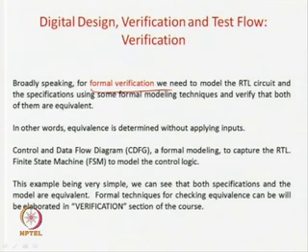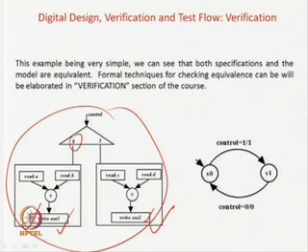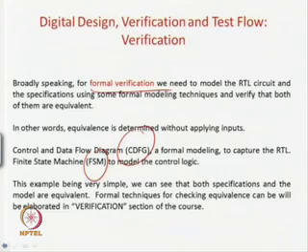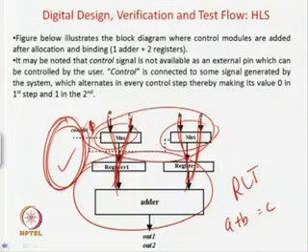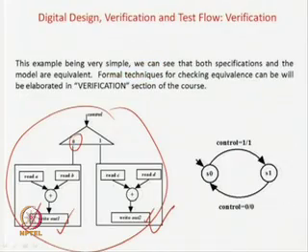So, what are some important models to capture the RTL design or the architectural design? There is something called control data flow graph and something called the finite state machine. For example, if you look at this, what is the data flow? You read A, read B and write out 1, read C, read D and write out 2, and there is a control. So, if 0, this is going to happen, and if 1, then C plus D is going to happen. So, this is actually the mathematical model of your whole circuit. This circuit is mathematically modeled via control and data path flow here.